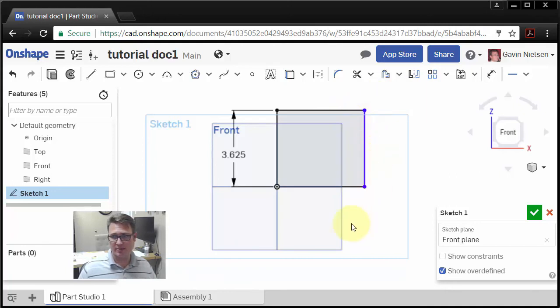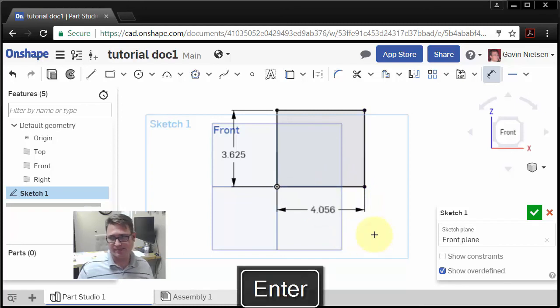So I'm limiting my degrees of freedom little by little. So I'm going to click on this dimension tool again, left click on it, and this time I'll show you we can do it by clicking. We can either dimension the length of this line, or we can do it this way, by dimensioning the distance between that line and then left clicking on that line too and dropping it somewhere. I'm pressing enter.